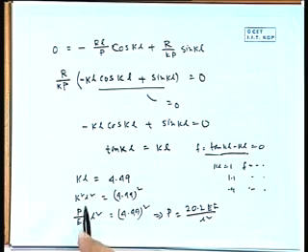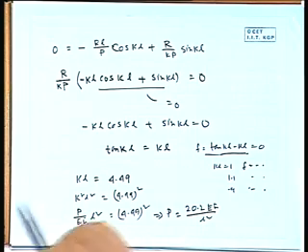So kl equal to 4.49, and the square of that is 20.2. So here P by EI, if you rearrange again it will be 20.2 EI by L square. Now we have the standard form pi square EI by L square. What is pi? Pi is 3 point something, squared.